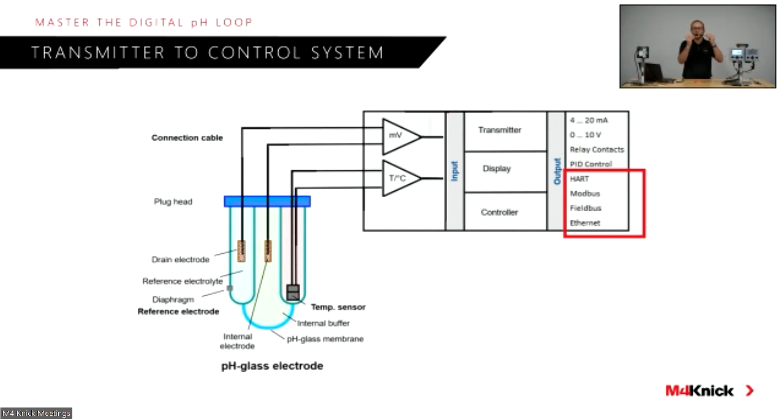And for today's purposes, we're talking about a digital signal, ones and zeros generated from the sensor via RS-485 from sensing element into transmitter. That transmitter may or may not have a local display, right? When we talk about digital sensing technology, we can do some really cool things with the transmitter because the transmitter does not need to store as much data. It doesn't need to store the calibration adjustments and things of that nature. So it can be displayless.